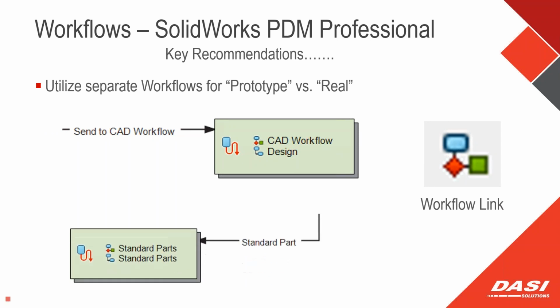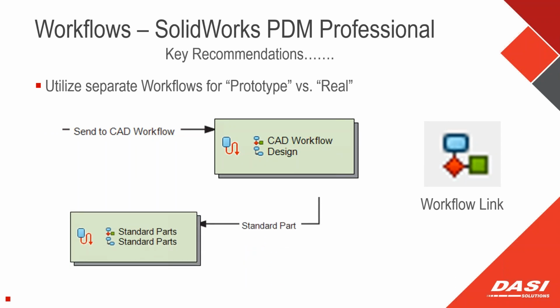And a lot of times we use these when we're trying to capture things like a toolbox part. Now, toolbox parts are SolidWorks parts, but we treat them completely differently than other SLDPRT files, mainly because they're standard components. They shouldn't be revision changed, but due to the mechanisms behind SolidWorks and the way that our configurations are added on demand to those toolbox parts, we need those to be able to work through workflows and be edited, but without being transitioned.